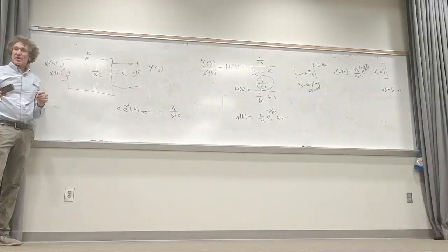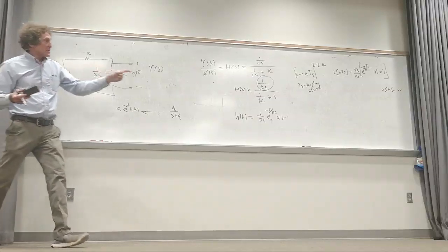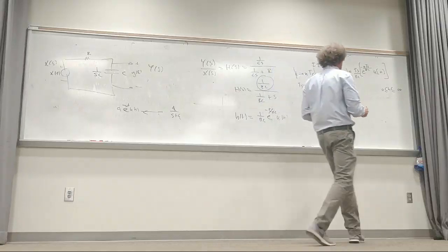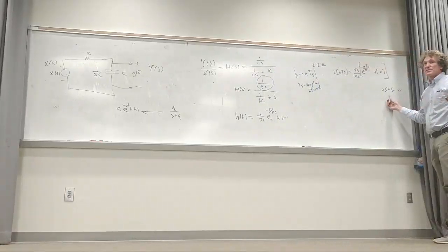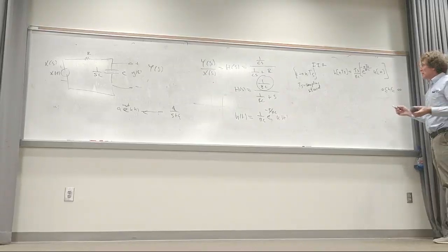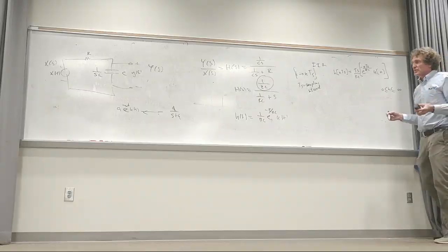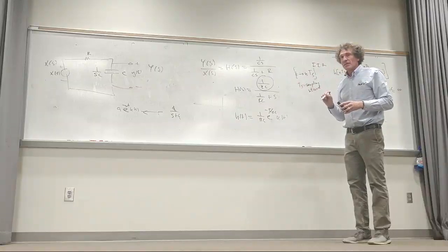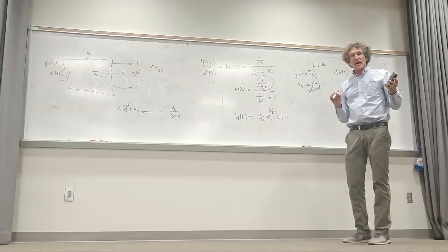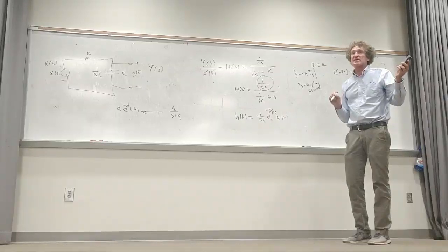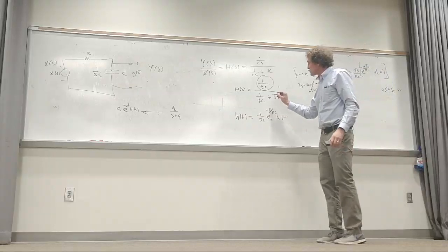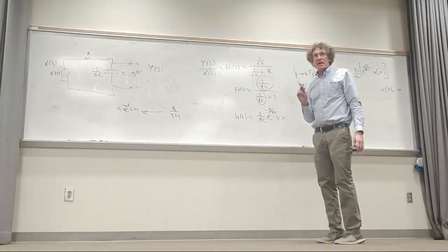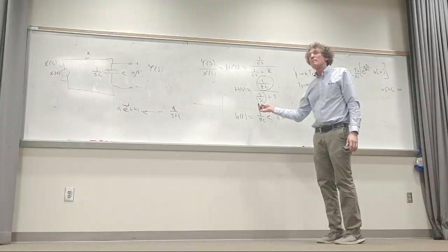If that's a low-pass filter right there, and you look at this stuff we just got here, you realize if we take a finite number of points here, it would be something that would do a low-pass filtering operation on your input, right? Do you all agree with that? Now here's the one thing about this one. If you just looked at this filter right here, the 3 dB point, the point where all of a sudden the output will be 70% of its maximum value on this filter, will be when S equals 1 over RC, or where the magnitude of j omega equals 1 over RC, or omega is 1 over RC. Do you follow me on this, class?